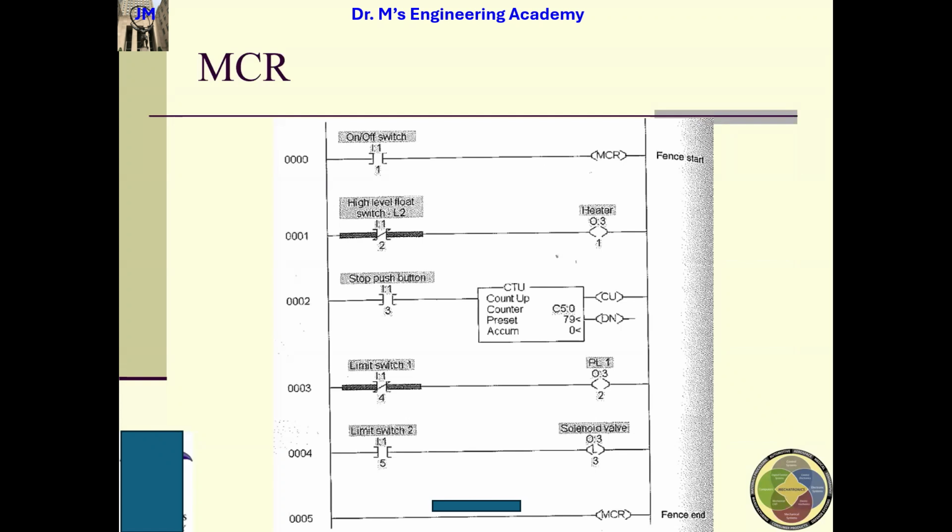But when we did the PLC start-stop switching circuit, right, after you finish this diagram, you turn the power on. You see the stop button is bold green, right, guys? That didn't happen for our group, but I saw it with other groups. If you don't have it in your group, that means your program is not right. I think you did not notice. Okay, whenever this guy is true, it is bold.